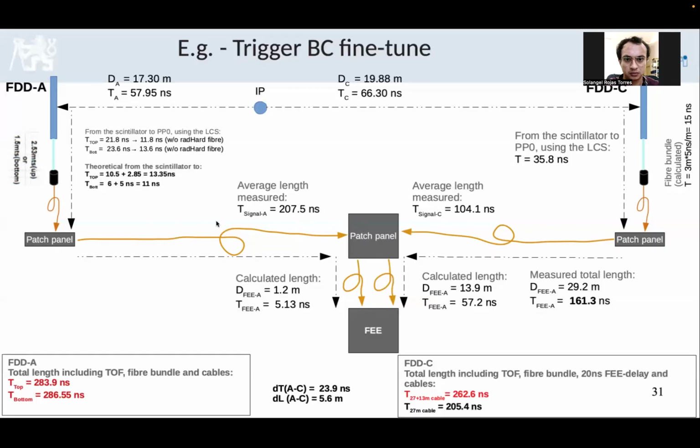So here I calculate the time of the light travel, and then the signal through these long cables, up to 200 nanoseconds even. And then even the short cables, like 0.1 meters, add about 5 nanoseconds more or less. And then you have the calculation of how much time it takes. For trigger detectors, this is crucial.